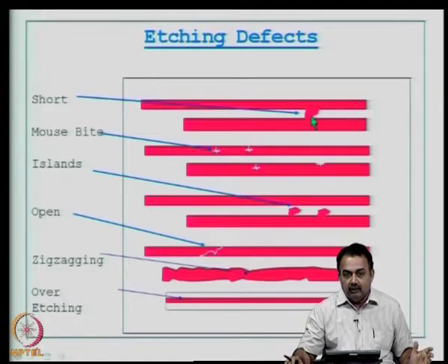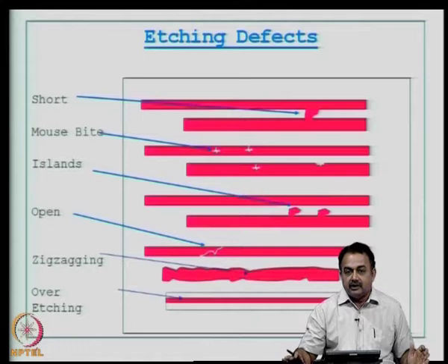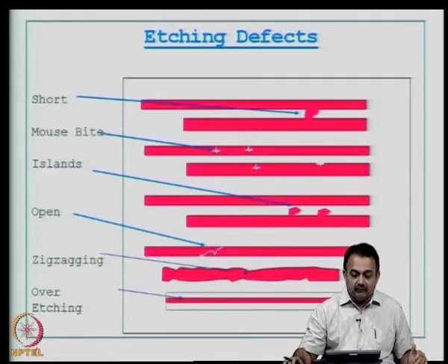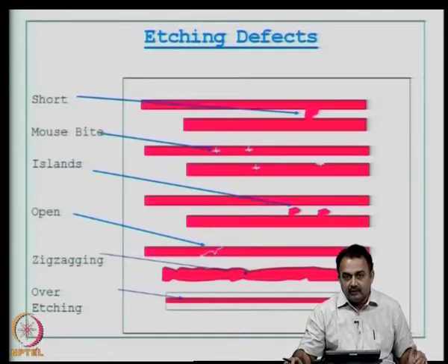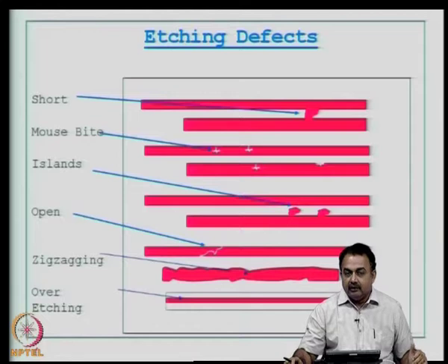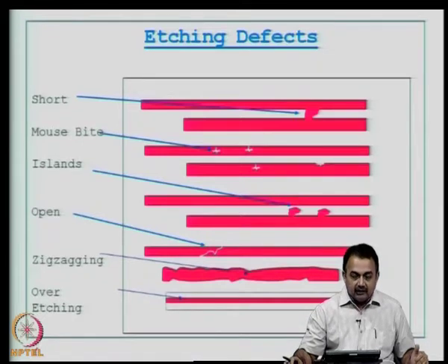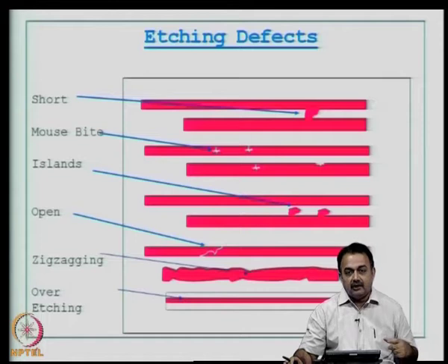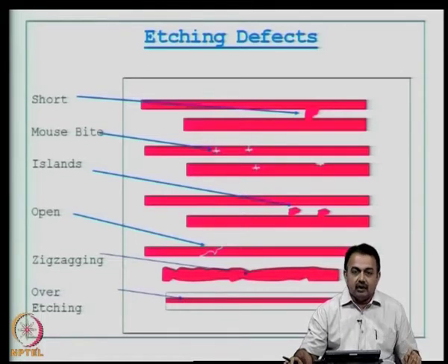One of the reasons could be that a strip of mask or photoresist is present there which you have not noticed. So, there is a problem with the developing process during the photoresist application or image transfer, or it could be that it has not undergone the right exposure in that particular area, or there could have been a bubble which has affected the exposure and it has finally got translated into copper.